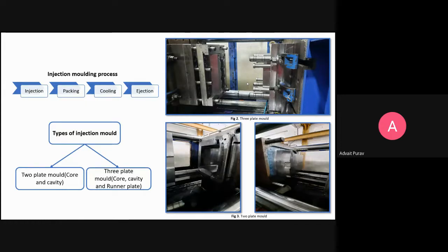You must have read about defects, maybe if you have studied casting or molding, there are a lot of defects like unfilled sections, uneven sections, flash defects. Those will keep coming. But as you keep doing the trials, keep increasing the injection pressure and adjusting it, your mold will go on getting filled, and after around 4, 5, 10 trials, whatever it takes, your part will be filled completely. So that is how it happens. Okay, sir.